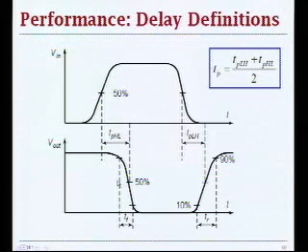It takes some time to understand the information from the input, and it will then finally settle to logic 0. So the time it takes a gate to process this information, and the time it takes this input signal to go between 50% of transition and appear at the output, this distance between these 50% points is called a propagation delay for high to low output.